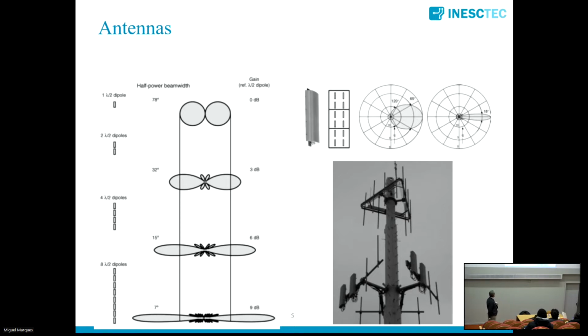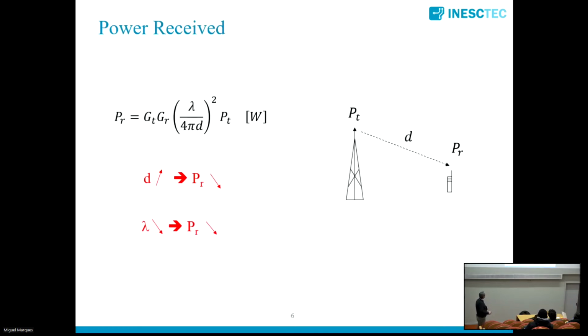Of course, then we compose and use sets of antennas in order to control the radiation diagram of these antennas. And we may put these antennas radiating more in one direction than in the other direction. And by doing that, we say that we are associating some gain to the antenna. But the point that I'd like to raise is that there is a relationship between the dimension of the antenna and the frequency that we are using.